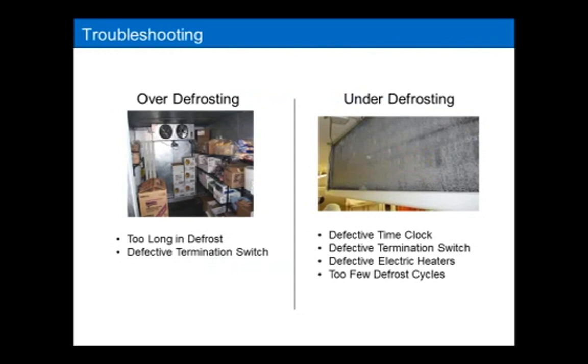Okay. So let me just go over some small troubleshooting tidbits, and then we'll open it up for questions. When it comes to troubleshooting, it's very easy to break it down into one of two problems. Either you're over defrosting or under defrosting the evaporator. Under defrosting, by all means, is the most common problem.